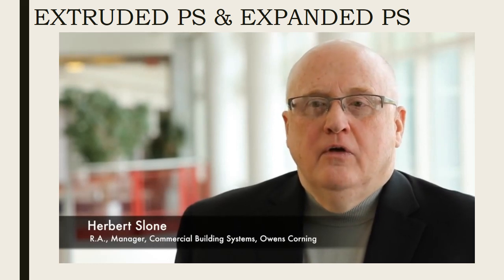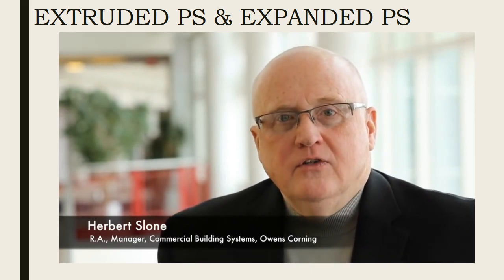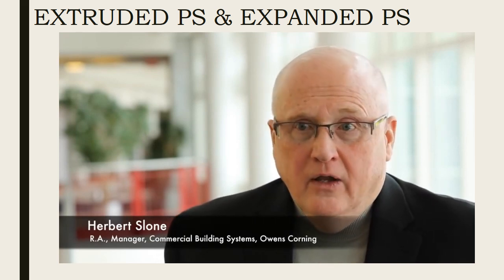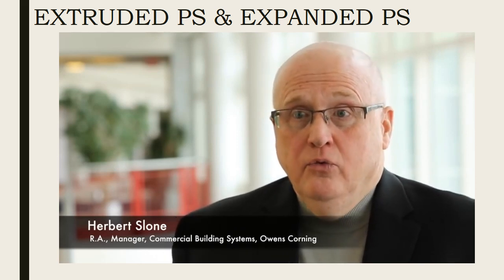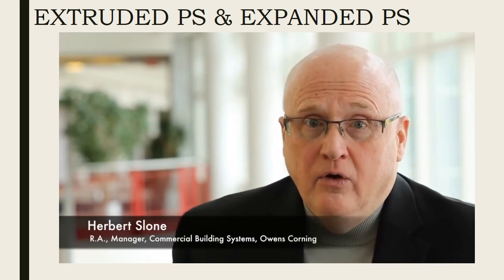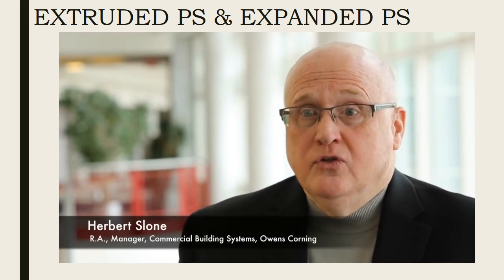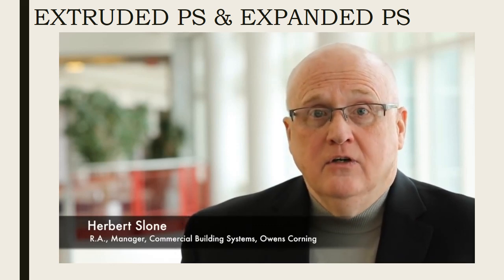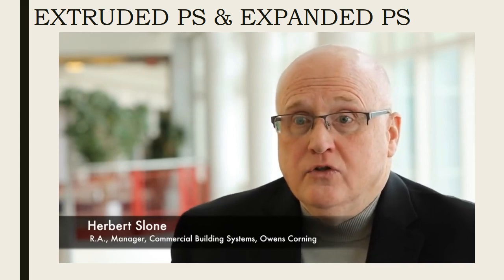Resisting water is critical for high-performance insulation because water is a good conductor of energy. So if water gets into the board, it lowers the thermal effectiveness of the board. Water allows energy to short-circuit or bypass its way through the board structure and really reduces the effectiveness of the insulating power. XPS, because it doesn't absorb water, doesn't have those short circuits in it. XPS is a closed cell structure and maintains its insulating power in the presence of water because water can't get into it and create those short circuits.